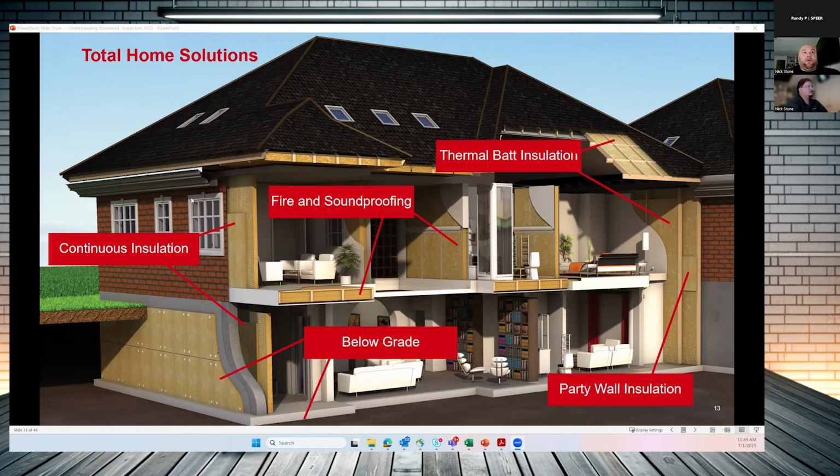So whether you're in that roof line, cantilevered overhang, or you just have a thicker, maybe passive house style build, we have some different offerings for all those different thicknesses. For the Comfort Board material, what you see here on the outside of the building, that's offered in 1-inch all the way up to 5 inches, essentially in half-inch increments. So depending upon what you're trying to achieve for an R value, if you're trying to do the perfect wall where we're getting our interior to cavity to exterior ratio to the correct point where condensation always forms on the outside of our WRB.